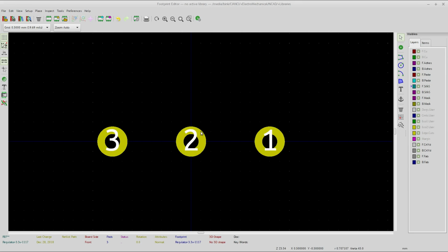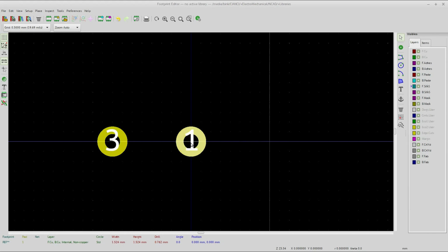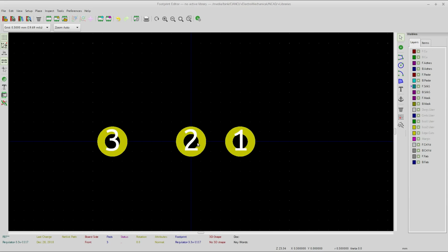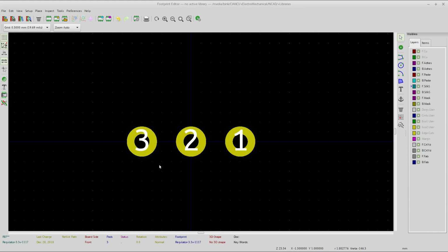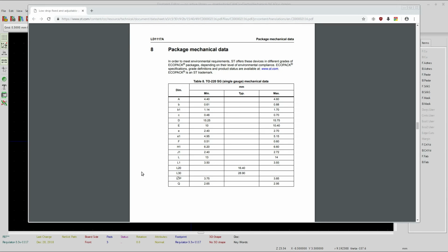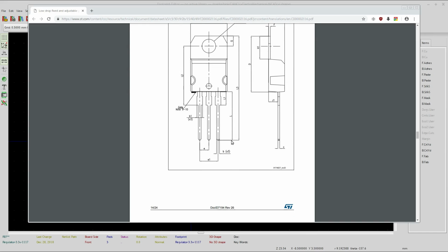So if I scroll in here, if I've got a pad right here, here's 1. So there's 1 millimeter, there's 2 millimeters, and there's our 0.5. So I need to move that. I got to count again. Ready? So 5, 10, there's 1, 1.5, 2, 2.5, right there. So that's where we need it. 1, 2, 3, 4, 5 things over. You see? Okay, now let's go back and take a look at the hole size.